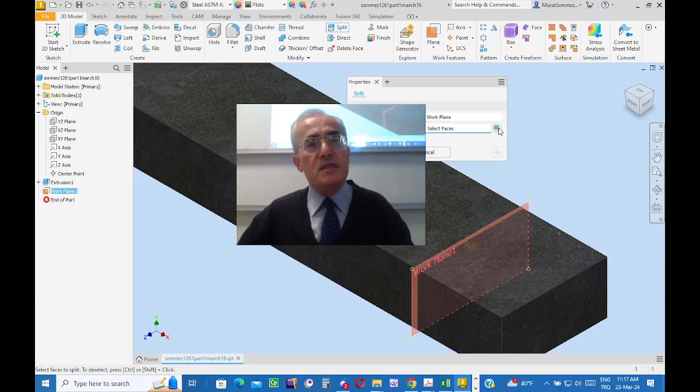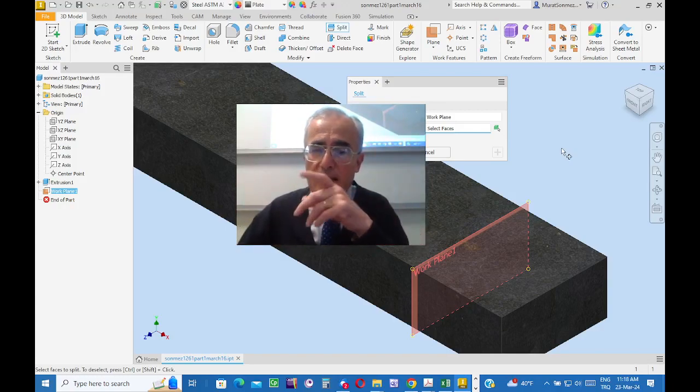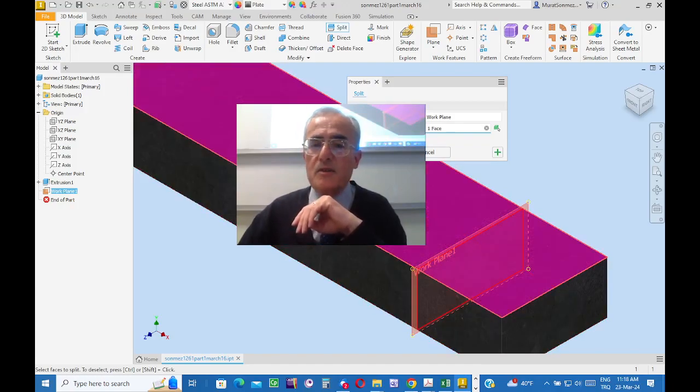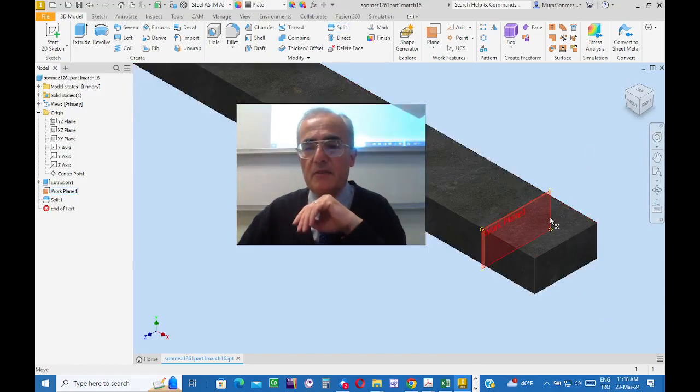If you click on the screen box, then Inventor can split the body. But here, for having sub-regions over the surface, to use different boundary conditions, well, the surface is to be split, not the body. So that is okay. Which surface? Indicate the surface with a click. And then say OK. Yes, now over the surface, we have two regions, this and that.